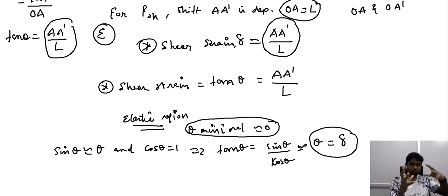So we have introduced what a shear loading condition is, and we have seen the distinguishing features of the response offered by the material under the shear loading condition. Using these distinguishing features, we now have a unique way of describing the response offered by the material under the shear stress, and this we refer to as the shear strain. There are two different ways of describing it, and for the elastic deformation, this shear strain is equivalent to the angular shift in the sides, the angle that is introduced when we observe a shift in the corners.